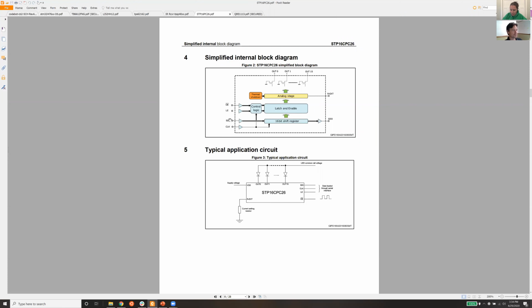And so as you put a binary 1, logic high, on here, and then you pulse the clock, on an edge of that clock it's going to clock into the shift register. And it's going to shift each bit that you clock in across so that you can control 16 LEDs. So you do a burst of 16 little pulses of the clock and set SDI, serial data in, high or low, and now you've set up all 16 LEDs to some value.